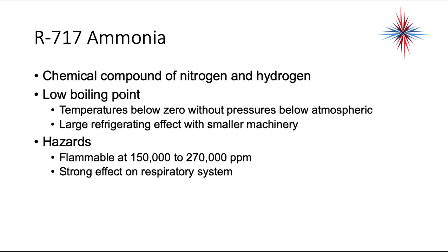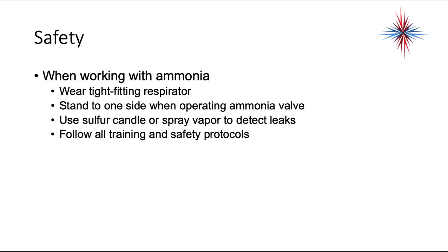There's some hazards with it. It's flammable at 150,000 to 270,000 parts per million. So it has a high flammability, and it has a very strong effect on the respiratory system. You cannot inhale it. When working with ammonia, you have to wear a tight-fitting respirator. Again, you cannot inhale this. You always stand off to one side when operating an ammonia valve.